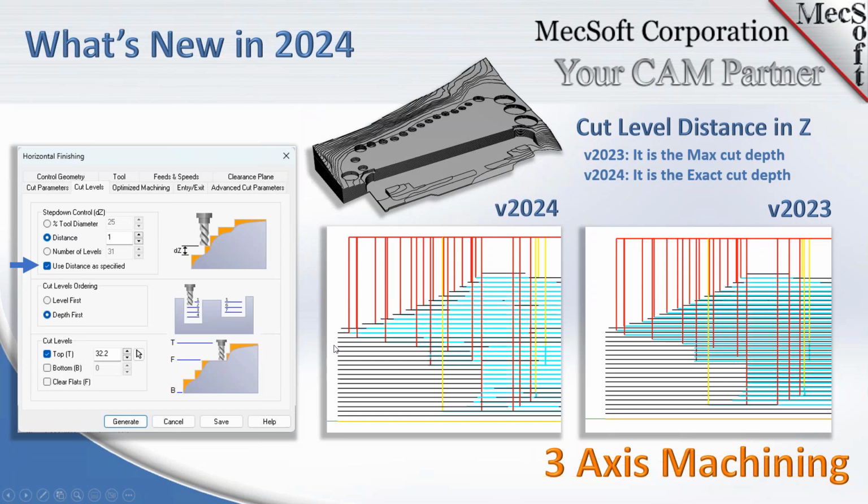Now this one, I like this one as well, because previously, if you may have run into this, if you were doing 3-axis horizontal finishing, you didn't always have exact control over the distance between the cut levels. Correct me if I'm wrong, Joe, it calculated the overall cut depth and then divided that by the maximum distance, and then it would fluctuate in between that. And I know I probably messed that up a little bit, Joe. Go ahead.